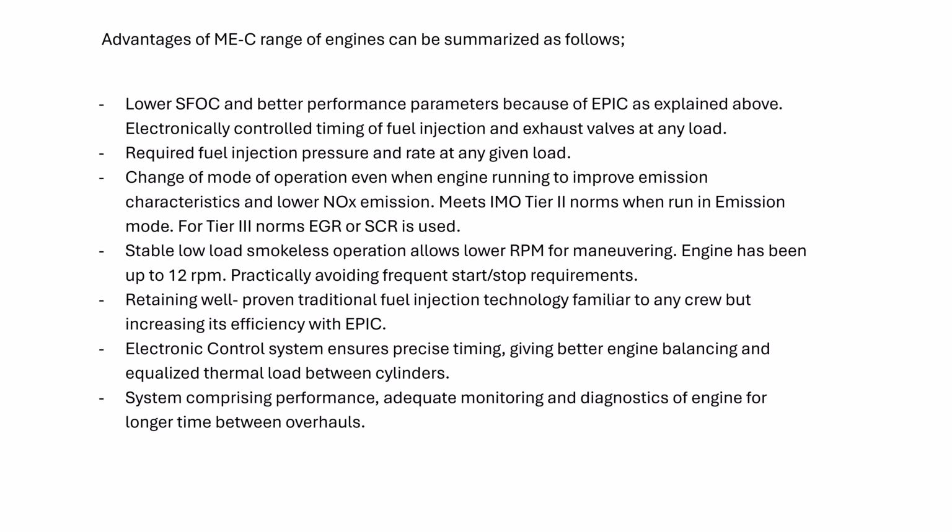Stable low load smokeless operation. The engine can be run down to 12 RPM, practically avoiding start-stop. Bring it to 12 RPM. You don't have to stop the engine and again give a kick. Practically the engine is stopped, the ship is stopped. Okay. For chemical tankers which are running in and out, much better.